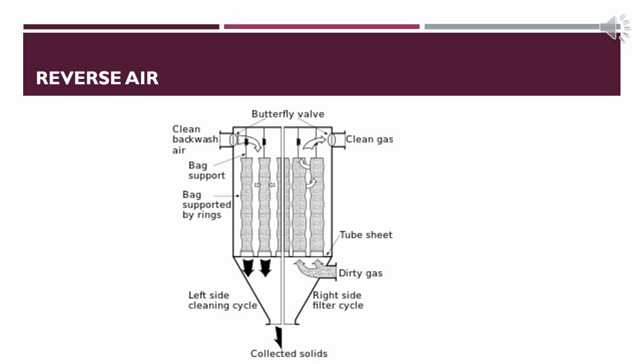In reverse air baghouses, the bags are fastened onto a plate at the bottom of the baghouse and suspended from an adjustable hanger frame at the top. Dirty gas flow normally enters the baghouse and passes through the bag from the inside, and the dust collects on the inside of the bags. Reverse air baghouses are compartmentalized to allow continuous operation. Space requirements for a reverse air baghouse are comparable to those of a shaker baghouse. However, maintenance needs are somewhat greater.